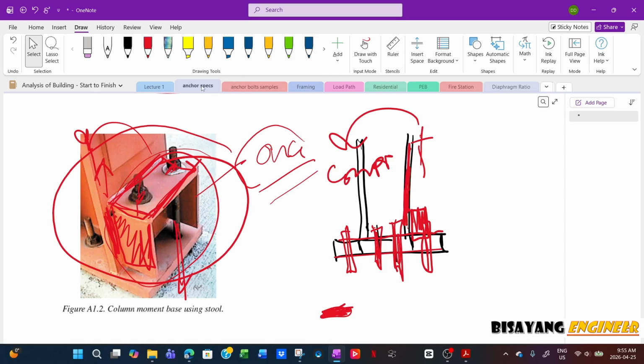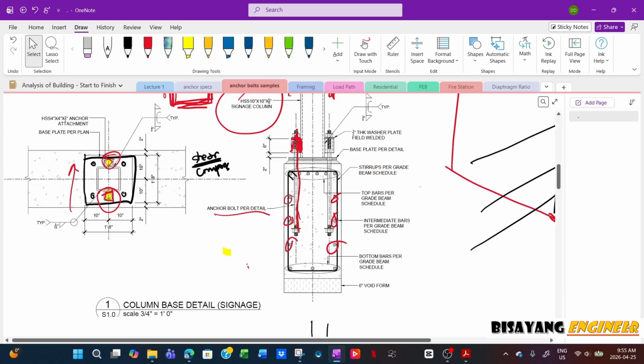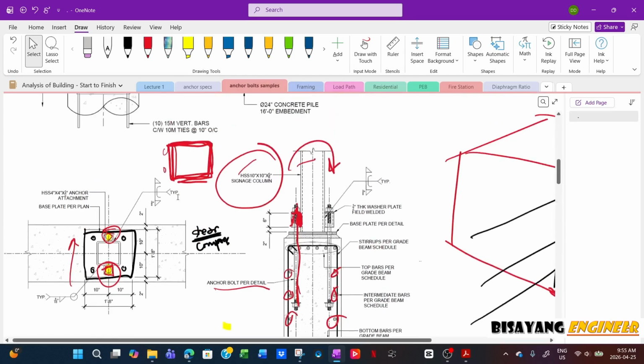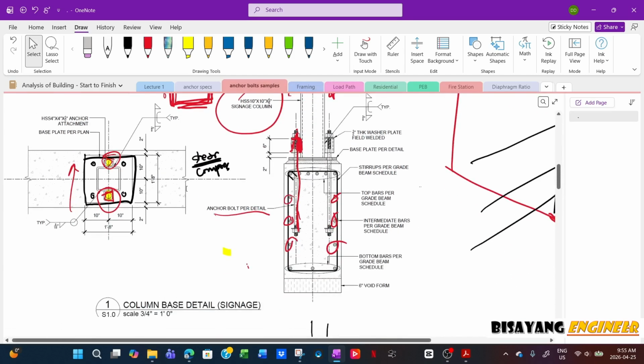And the reason I specify that HSS is that in other parts of the building I already used this one. So 4 by 4, 1/2 HSS, I think the column at the penthouse. Maybe during fabrication they have some extra, so they just throw that there. I only need four anyway. So two on each column and then the other column.